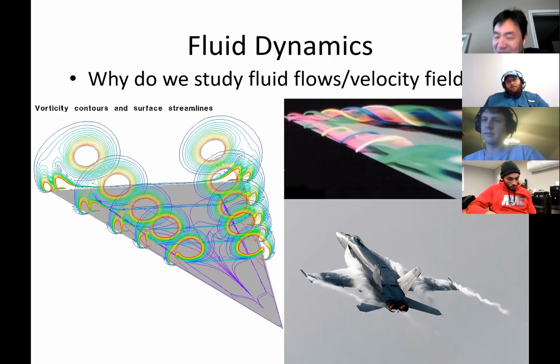Because under acceleration, when you're taking off, you want the low pressure on top of the wing and high pressure on the bottom. Exactly. The aircraft is sucked up. That's how you have lift and flight. The lift is the pressure difference between the bottom and the top of the wing, right? So the bottom has nothing there, just normal, regular atmospheric pressure. On the top, you have strong vortices. Then you have low pressure. Just remember, vortex is associated with low pressure. So that's the taking off, positive lift.